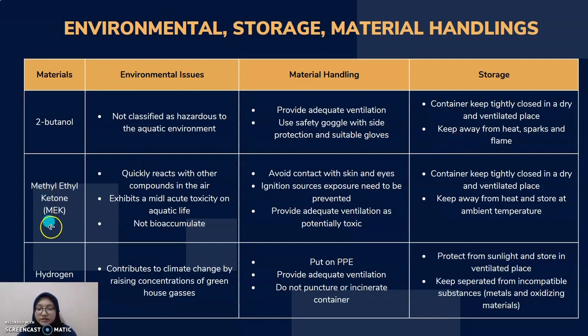The second material is our product, which is methyl ethyl ketone, MEK. It quickly reacts with other compounds in the air and exhibits a mild acute toxicity on aquatic life, and it does not bioaccumulate. The user needs to avoid contact with skin and eyes, and ignition sources exposure needs to be prevented. The user needs to provide adequate ventilation as it might be toxic. The storage for MEK is the container needs to be tightly closed in a dry and ventilated place and away from heat and stored at ambient temperature.